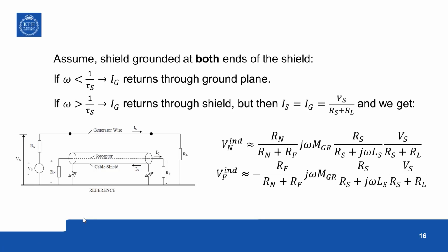But often the high frequency currents may return not via the rails but via the wagons, and it may damage even the bearings because of those currents. So in AC, the currents would like to return through a path where the coupling flux is minimized.